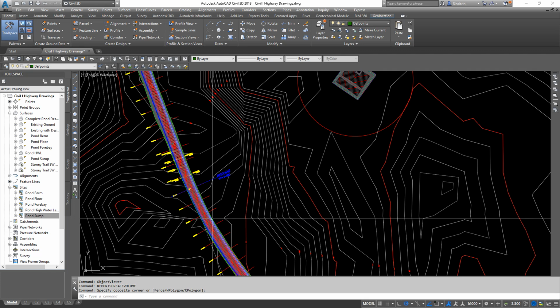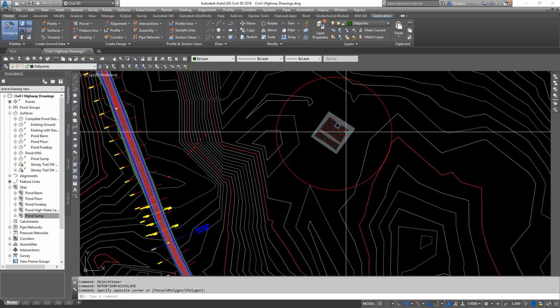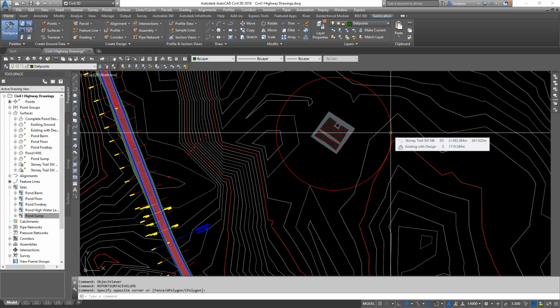Again, to ensure that all water flows to the pond, that is something that should be done, but getting the pond done the way it is is a hard enough task. So again, the ditches and the inlet are just 2 more steps. You would need an outlet on the pond just in case it does flow over. You don't want it eroding your berms.